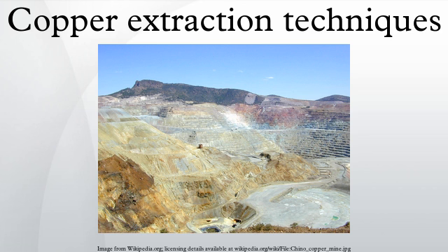Smelting. The initial melting of the material to be smelted is usually referred to as the smelting or matte smelting stage. It can be undertaken in a variety of furnaces, including the largely obsolete blast furnaces, reverberatory furnaces, flash furnaces, Isasmelt furnaces, etc. The product of this smelting stage is a mixture of copper, iron and sulfur that is enriched in copper, and which is called matte or copper matte.